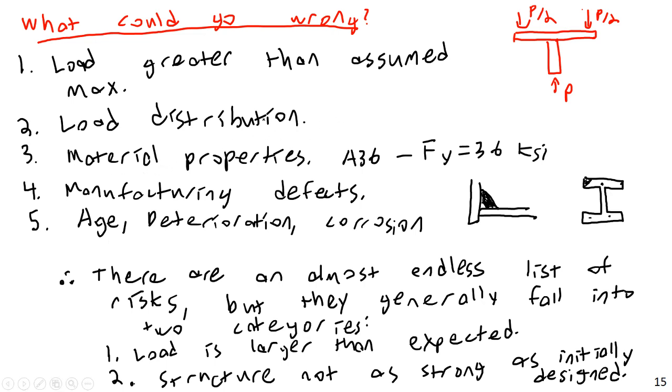If I wanted to make sure I absolutely minimize the chance of having material property problems, I could buy from a highly reputable steel mill and make sure they double checked and triple checked their batches. I could actually run some material tests of my own. I could take samples of the material and test it in a strength testing machine, in a tensile tester, in a shear tester, whatever.